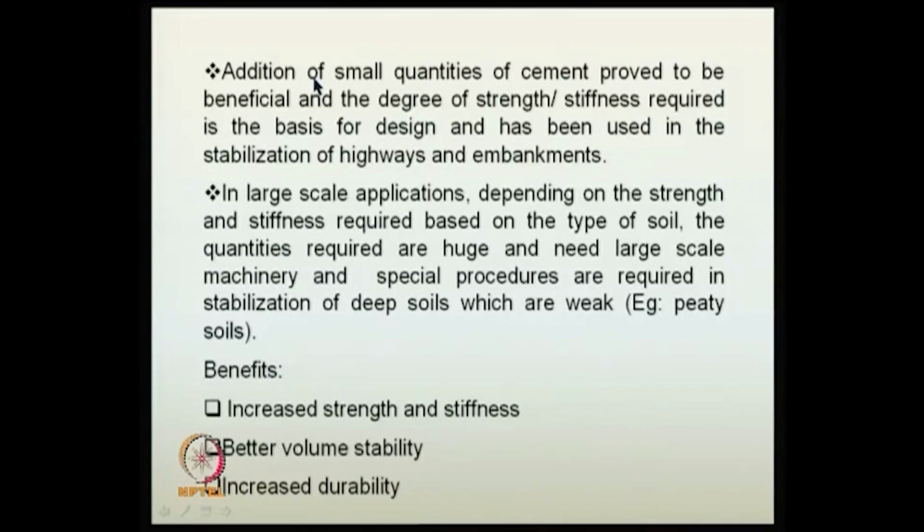If you use small quantities of cement, the addition proves to be very beneficial, and the degree of strength and stiffness required is the basis for design, and it has been used in stabilization of highways and embankments. Like we have seen earlier, if the CBR is low, we add some sort of binding agent like lime, and the CBR increases. Similarly, we add cement here to see an increase in strength as well as stiffness. Both are required, because we need the bearing capacity to be increased, particularly in the case of highways and embankments.